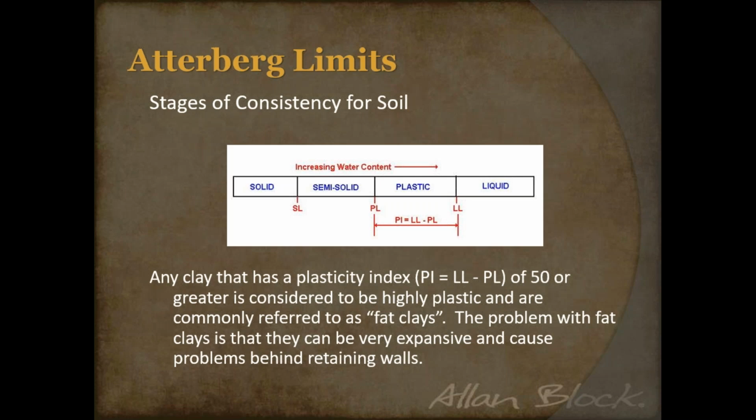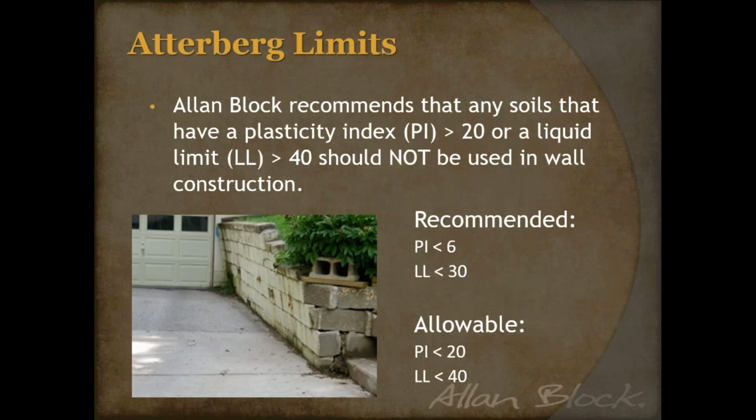A point of reference is that for most soil classifications, anything that has a PI greater than 50 is considered a fat clay, or highly expansive or plastic. And those are problematic. In fact, most geotechnical engineers will say that anytime you've got those very fat or plastic clays, we don't want to use those in construction, and definitely not in retaining wall construction. When you have those highly expansive clays, they can absorb moisture, or on the flip side, they can actually collapse, creating settlement as they dry out, because that's how sensitive they are.